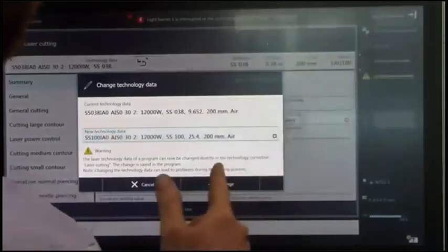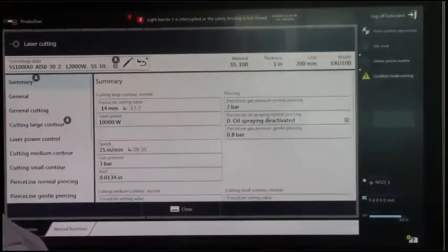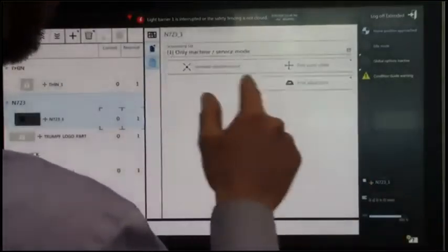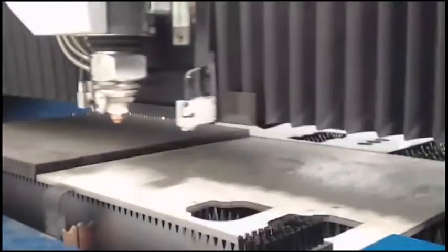All right, on to the final stainless steel, our 1-inch. So again, this is going to be the max capacity for air cutting. You can go thicker on this machine. It's got a lot of power. To use nitrogen, you can go a little thicker, but we're a little limited on air cutting just because of the lower gas pressures.